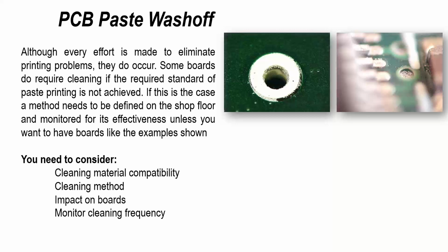Sometimes materials are not compatible, so you're mechanically removing the material. Obviously, you're mechanically removing the solder alloy, the actual particles, but all the fluxing materials, what you want them to do is to go into solution, so you're proving the material is compatible. Your cleaning material or chemistry must be compatible with the board as well and not affect the wettability or solderability of the board. If you look at copper OSP, that can be affected by cleaning agents, so be aware of it.